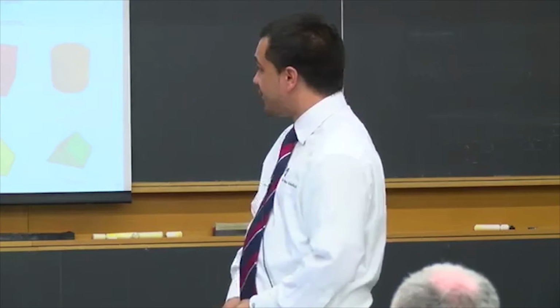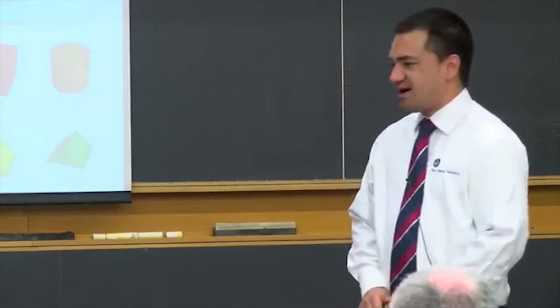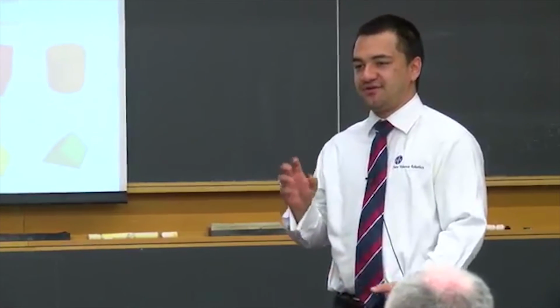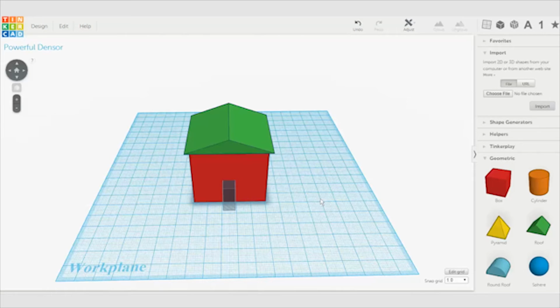All right, so at this point, now we have 3 objects all fitting together into one house that we have here. Sometimes if you click in the wrong place, you might accidentally knock an object off to the side, and then you have to redo the steps that you did before. That's never any fun, so I'll show you how to actually group these parts together so that when we click on part of it, it'll all move together as one cohesive unit. So, as we did before, let's select all of the objects by dragging and dropping a box around everything to select everything.